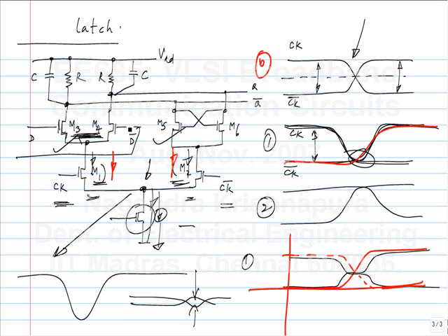I think we discussed it yesterday, right? So, we know how to tweak the sensitivity, setup and hold times, and probably the clock to Q delay of the latch as well, right. Of course, you may not have freedom to optimize everything, but if you want one of them skewed in favor of the other, then you can modify one of these things, right. And also, if you get a certain setup and hold time, you should be able to identify the cause for the limitation, okay. Let's say you can't go beyond a certain setup time, 10 picoseconds. Why not? So, that will impose a limitation on the speed, right. So, you should be able to figure out why that's the case.